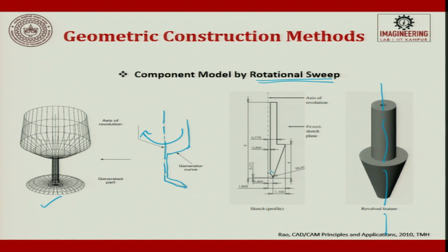Look at it here, how beautifully they have done. So, this portion is like this. If you want to sweep it around, you can sweep it, and at the bottom you can get this done. So, you draw it in a zoomed manner and then reduce it to normal scale and sweep it, or you sweep it and then expand it, you can do that. So, here this gives you a very easy way of constructing a 3D solid from a 2D basic drawing.